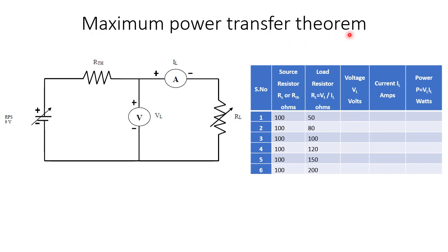Maximum power transfer theorem. In this video, we are going to verify maximum power transfer theorem using TINKERCAD. This is the circuit diagram for maximum power transfer theorem. In the circuit diagram, we have a 9-volt power source, Thevenin's resistance, a variable load resistance, a voltmeter to measure voltage, and an ammeter to measure current.